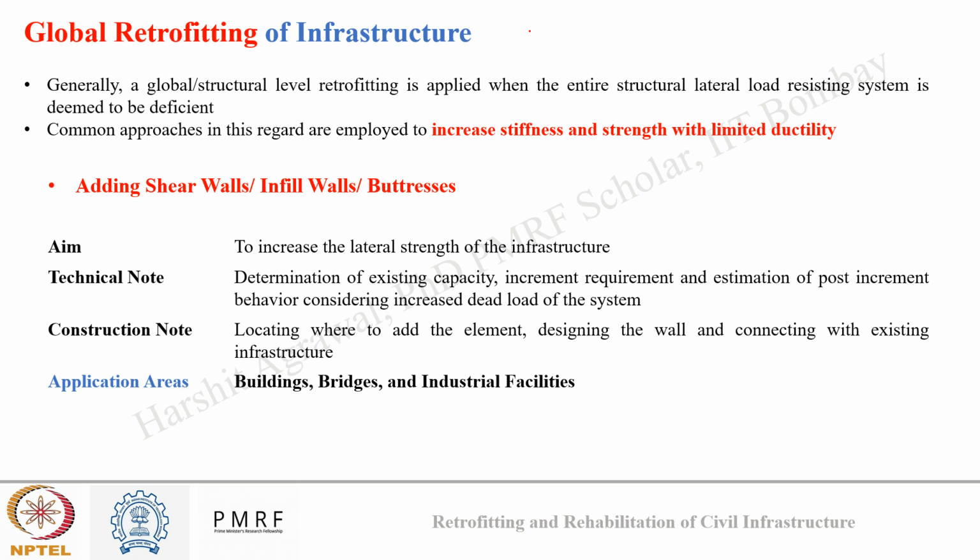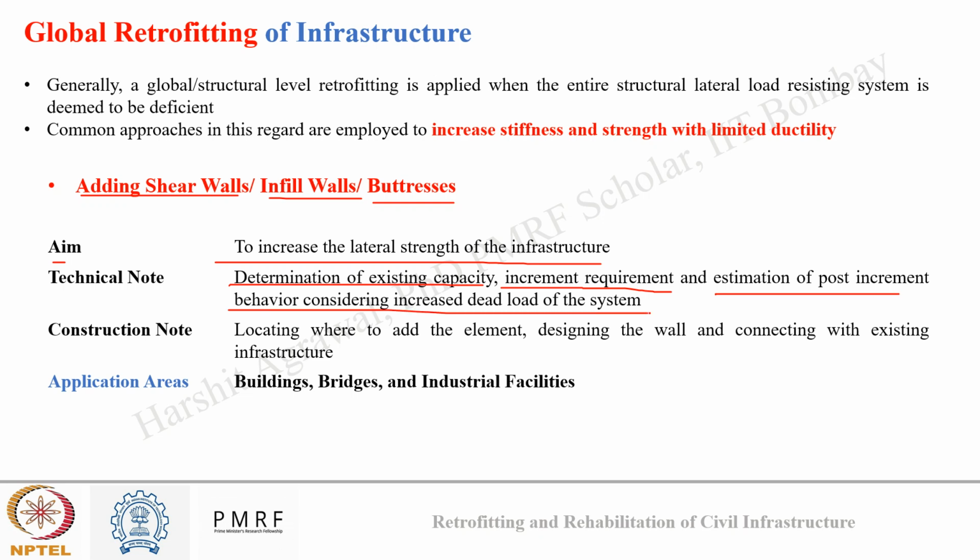The first technique can be adding shear walls, infill walls, or buttresses. The aim of these is to increase the lateral strength of the infrastructure. While opting for these techniques, we must keep in mind to determine the existing capacity of the structure, the increment requirement, and an estimation of post increment behavior considering the increase in dead load.